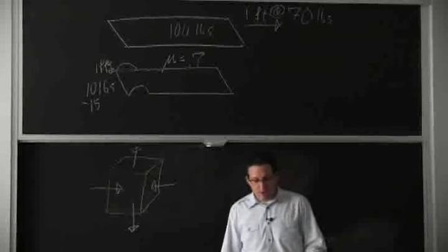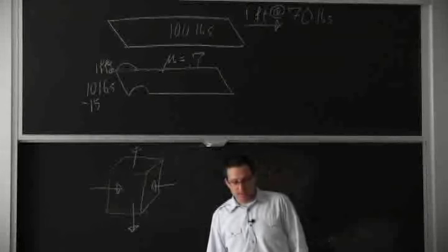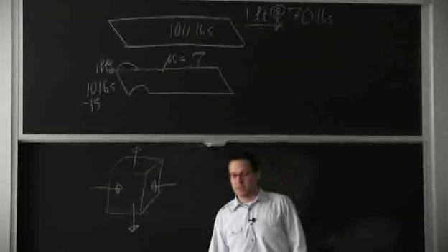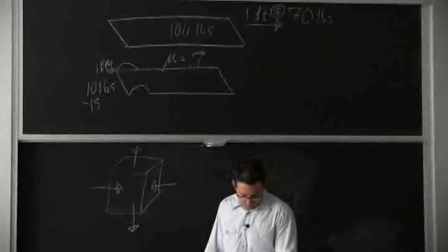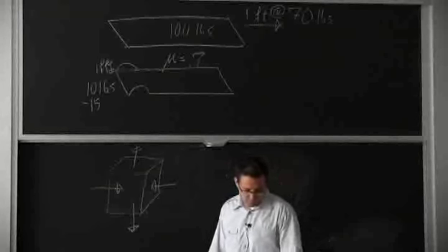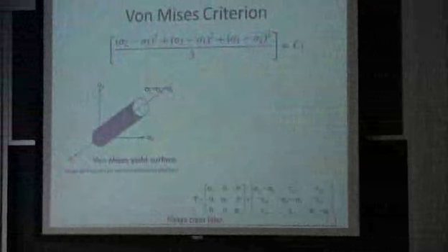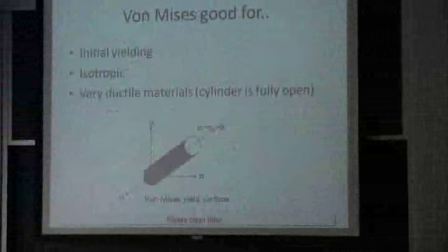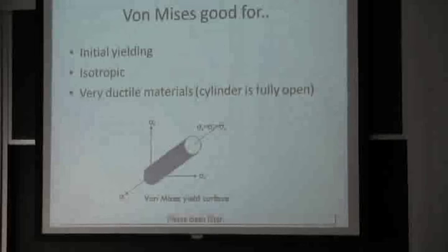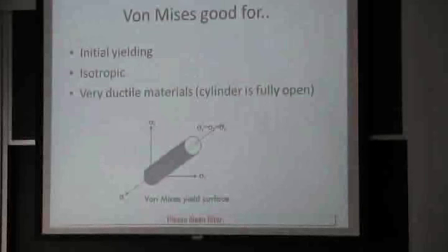And that all comes back to that difference of principal stresses equation, the equation we just talked about here, the top equation. Because we're reducing the difference. So now we can apply more stress before it yields. Okay, so we use von Mises to know when it will start yielding.